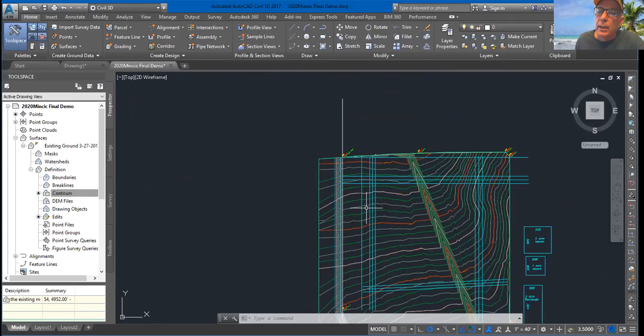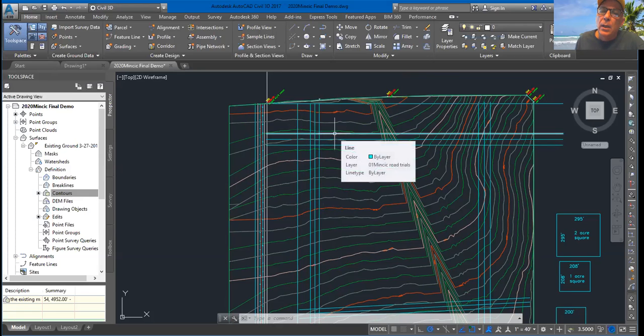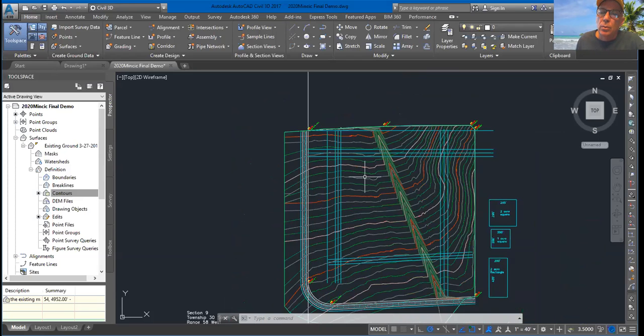But for our planning tools right now, we're just going to go ahead and do some preliminary planning with this. So the first thing I'm going to do is I've decided, okay, I'm going to start out with this main roadway. This is an 80-foot wide roadway. I did say that I want to be able to create parcels in this area that are at least 1 acre. So what I have done here is I've done a couple of things. I've looked at this roadway and said, okay, what if I decide I'm going to come over here, put in my main roadway to start here, travel along here, and travel all the way through here and exit out right here.